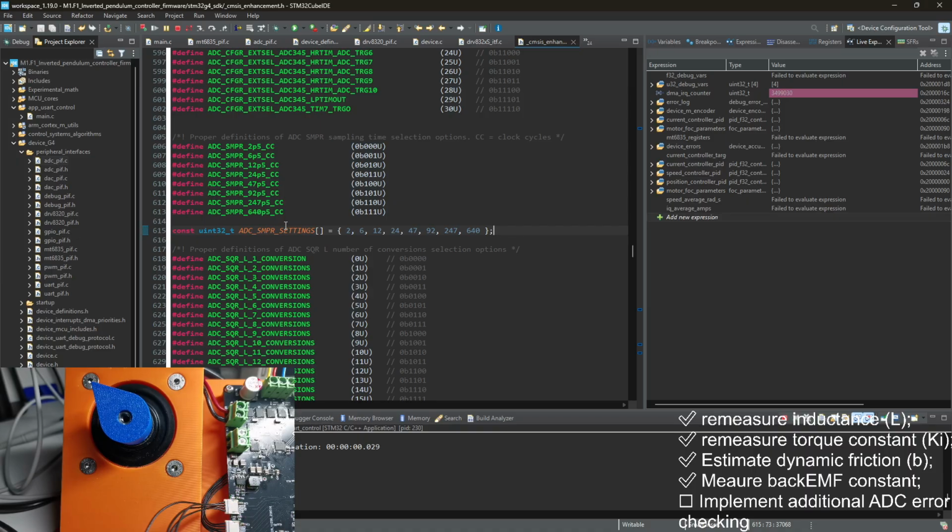Unless, of course, oh no. Or actually, hold on a second. No, you will have a free run if you just enable all the PWMs to the single value. This will mean that high side transistors are always closed and low side transistors are always open. And this will be a free run. Right? Or does it actually mean that?